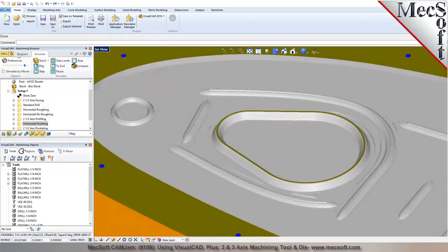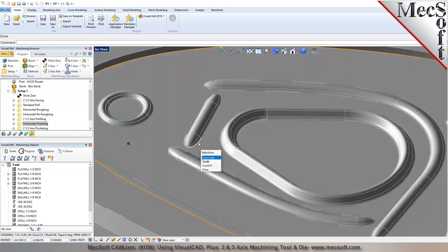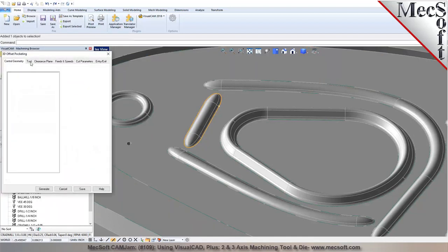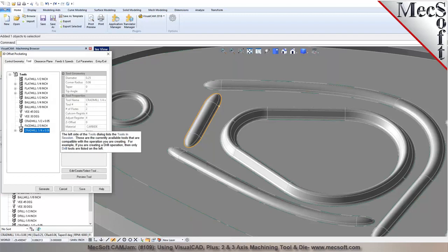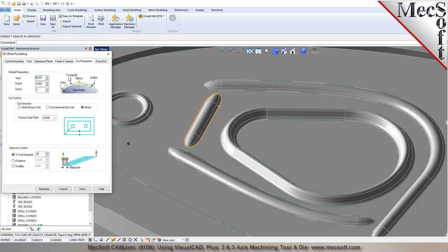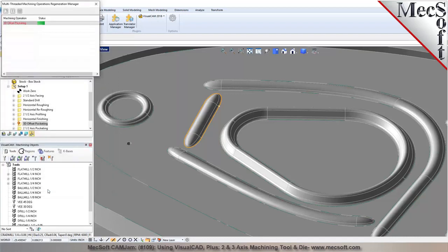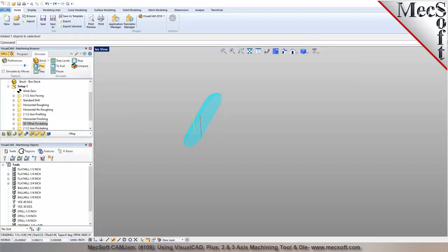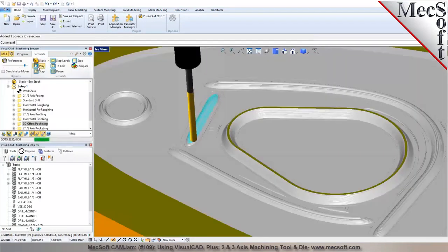And we can go back and apply other toolpath methods. So for example, in this area here, I can pick this and use a method called 3-axis 3D offset pocketing. This is known as a constant step over machining, or also a constant scallop machining method. You can use this by picking boundaries. You can choose to start inside and work your way towards the model. You can specify a step over, so that'll create a constant 3D step over machining toolpath. Look at the very fine details that you can achieve with this toolpath method.